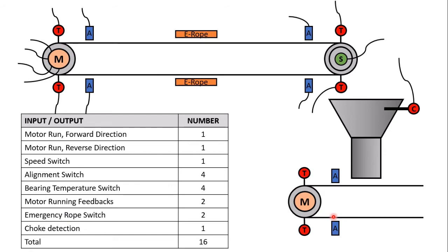You need equipment that is fit for that environment and will be able to collect data to and from the PLC. So with this being said, the idea is that we create input and output networks or I/O networks below the PLC layer. These networks can be scalable based on the amount of input and output signals that we have. The equipment is cheaper compared to PLC cards, and then we can have 1 or 2 cables running long distances from the field to the PLC.